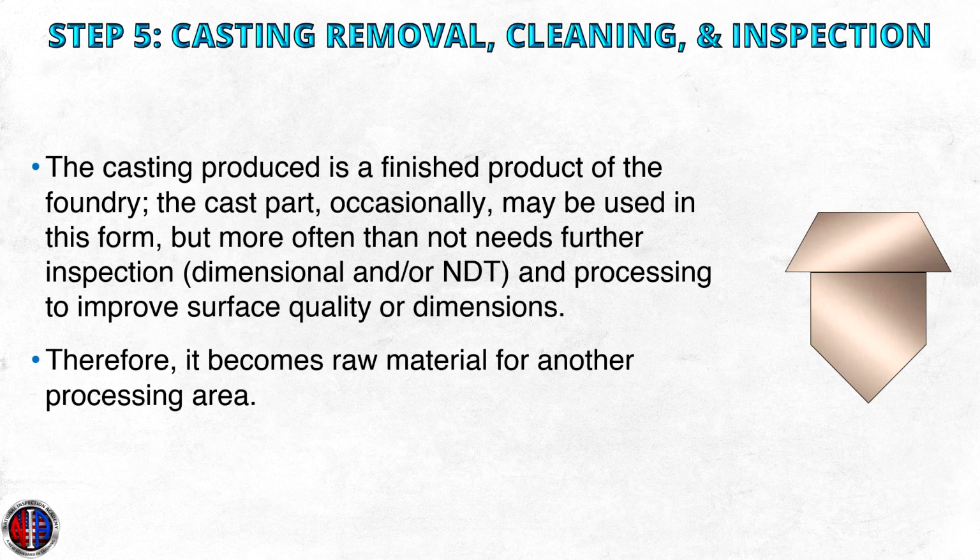The casting produced is a finished product of the foundry. The cast part occasionally may be used in this form, but more often than not needs further inspection, meaning dimensional and/or NDT, and processing to improve surface quality or dimensions. Therefore, it becomes raw material for another processing area.